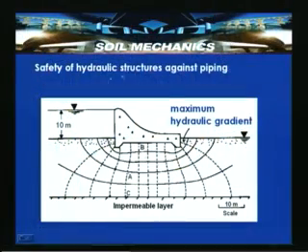So let us consider safety of the hydraulic structure against piping. For example, if this particular structure is constructed and there is no cut-off sheet pile wall here, this particular zone may be prone to failure.